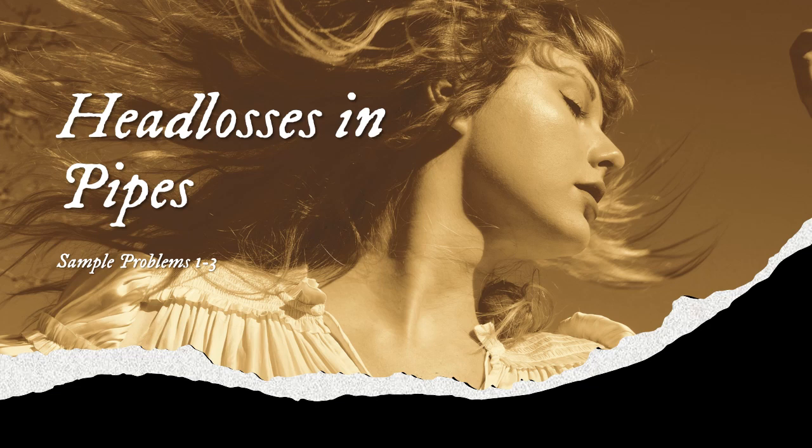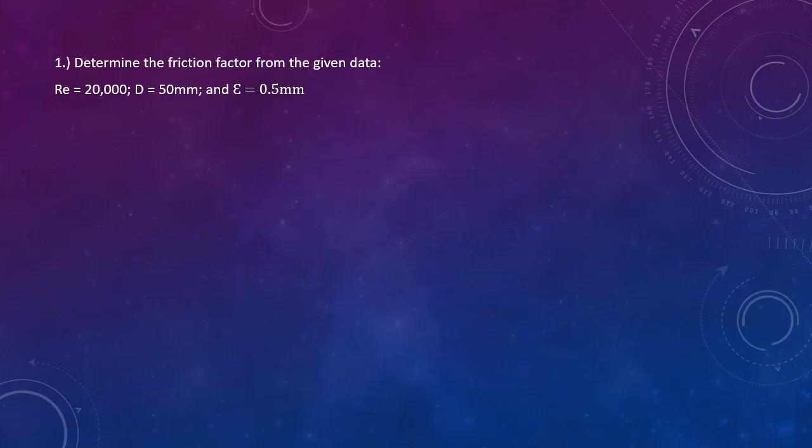In this video, I will solve sample problems 1 to 3 in head losses in pipes. Determine the friction factor from the given data. Reynolds number is 20,000, diameter is 50 millimeters, and absolute roughness is 0.5 millimeter.